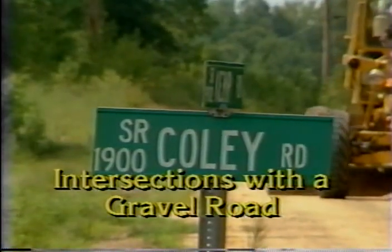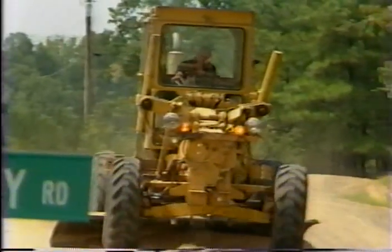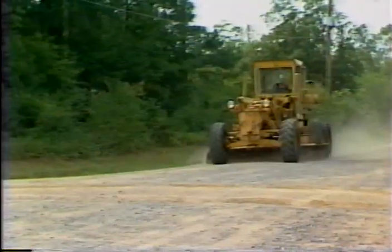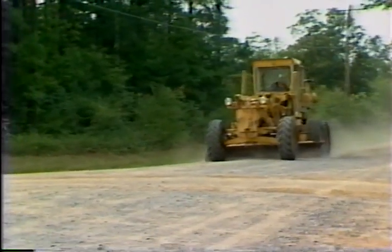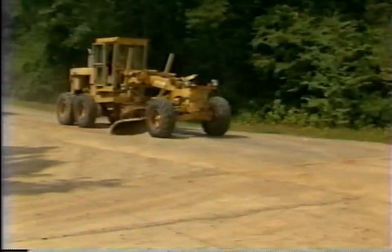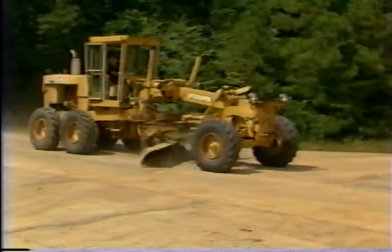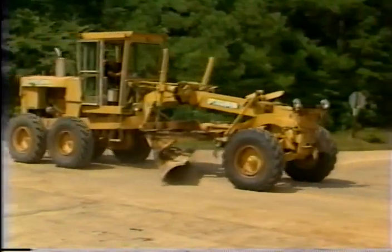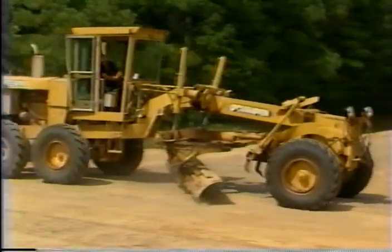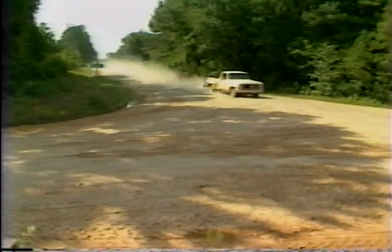The first special situation is the intersection with another gravel road. In the machining operation, gradually eliminate the crown, beginning 50 to 100 feet back from the intersection. Continue this transition such that the crown is totally eliminated at the intersection point. Follow this procedure for all 4 legs of the intersection. This means that the intersection is essentially flat, allowing smooth transition for a driver passing through the intersection.